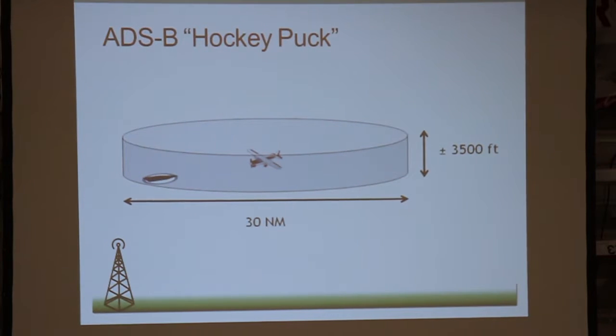So if you don't have ADS-B out in your aircraft, I get the question a lot, will I get traffic? You're not guaranteed to get traffic. If you're outside here, you don't have ADS-B out, you will just be seeing traffic that's close to this guy. And if there's another one that's outside of it, then you won't see him on your UAT reception. So oftentimes when you're close enough to an ADS-B out aircraft, if you're around here, you'll get traffic that's good enough.